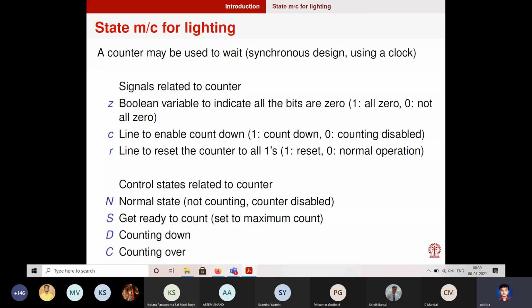So basically you have a clock which measures time at some interval, and that clock decides when this change in state can happen. This is a nice situation, because you need not bother about what happens in between. You only look at the system at these points. This makes the circuit simple. The other case is where change can happen anytime in between; there is no clock as such. There is nothing to maintain time. It's called an asynchronous system. It's kind of event driven.